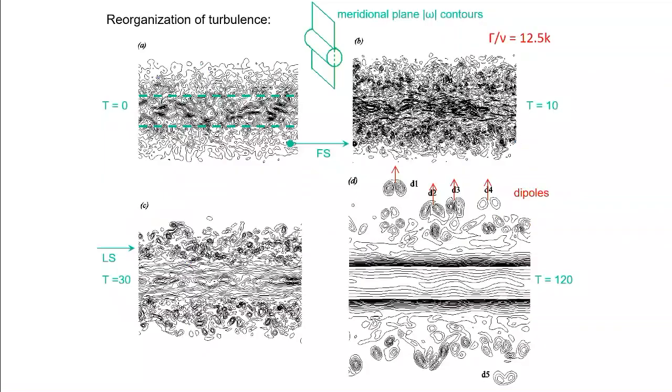But here is just one example where he studied the vortex column embedded in fine-scale turbulence, and you see the process of how the small-scale turbulence evolves by the effect of the coherent structure, essentially organizing the fine-scale turbulence into a series of dipoles that are vectored radially outward from the center of the vortex.